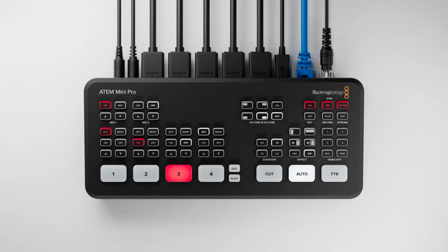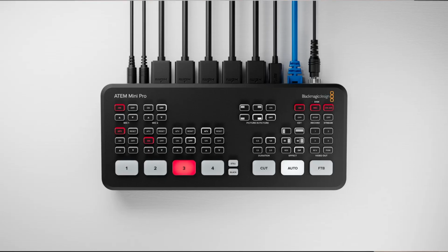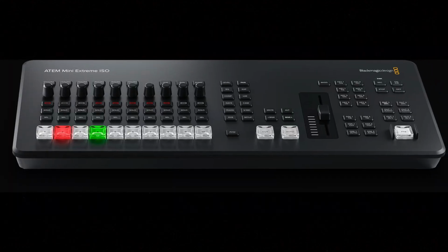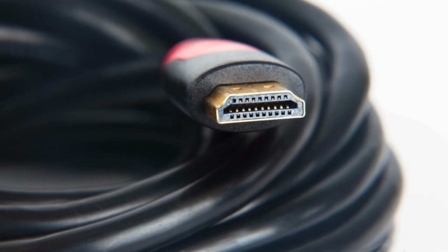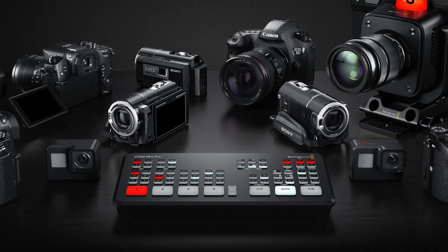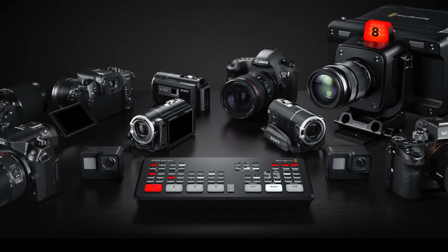The A10 Mini Pro has the option to come in either HDMI or an SDI standard, with either 4 or 8 inputs. SDI is a more professional standard for its reliable video cables with locking connectors and a much further run distance before you experience signal loss, compared to the consumer-friendly HDMI. HDMI has the advantage, however, of working natively with many consumer-grade cameras you might already have, including the Pocket Cinema camera, which does lack SDI.